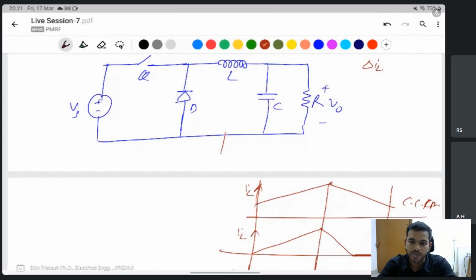Lithium ion batteries have a BMS, battery management system. It has its own controller for overload control, undervoltage control, overvoltage control and so on. That controller is fixed for output current. If you draw 5 to 6 times the full load current, it behaves like a short circuit. It sends a signal to the BMS controller as a short circuit fault condition. Then the whole supply is stopped.